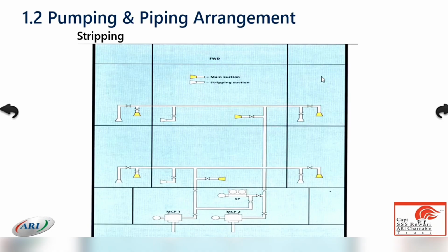So all the oil from the tank is flowing, give a stern trim, flowing to the well, and there's a small kind of a tub, you can say, within the tank itself, and the oil is flowing into the tub, and you have these bell mouths inside those tubs, which are used for stripping. It becomes very easy. No clingage, no obstructions, no stiffening. All stiffening is on the ballast side, on the other side. So that has brought big advantages in stripping the tanks.